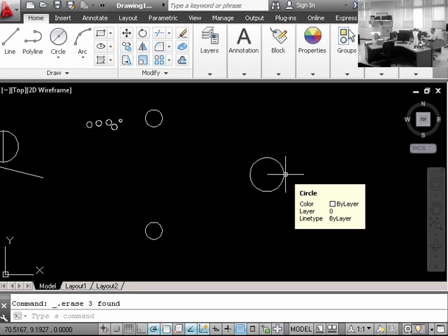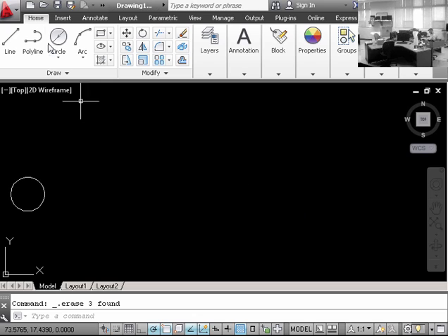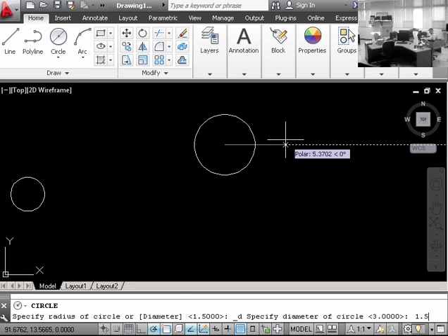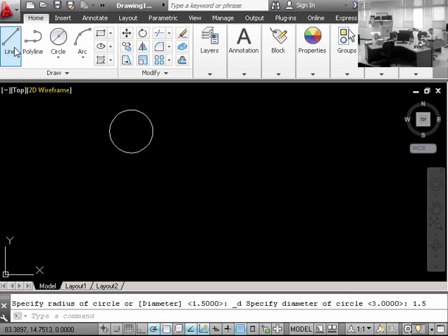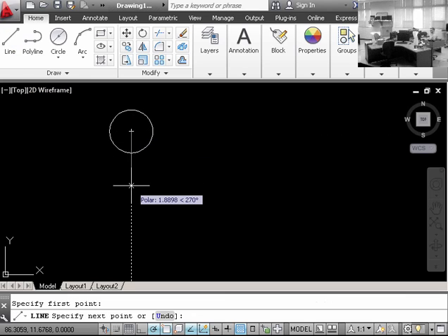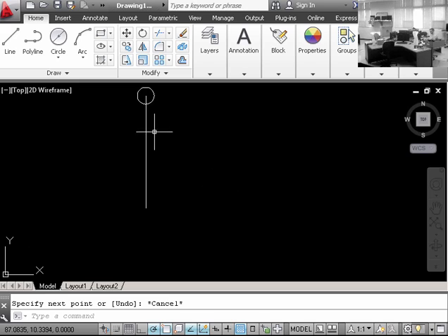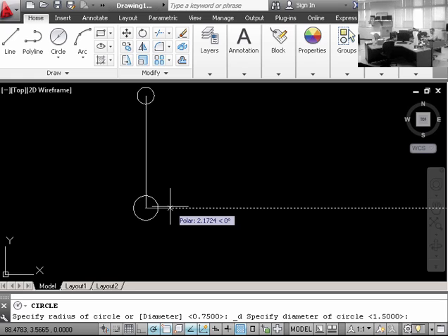Questions right off the bat? Yep. When you put your first circle on, I'm trying to figure how you get down the line. I drew a circle, 1.5 diameter, with me so far. Line command, click the center, point it down, type in 10, enter, escape. Just like normal, like we did our previous line commands. There's a 10-unit line, now it gives me a locking point to lock onto this, 1.5, and there we go.